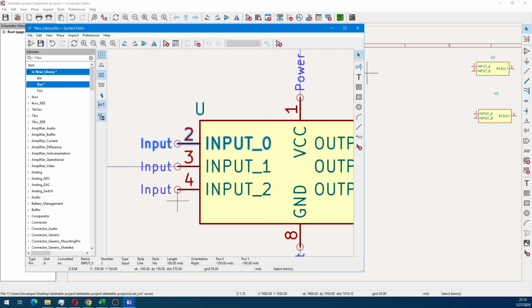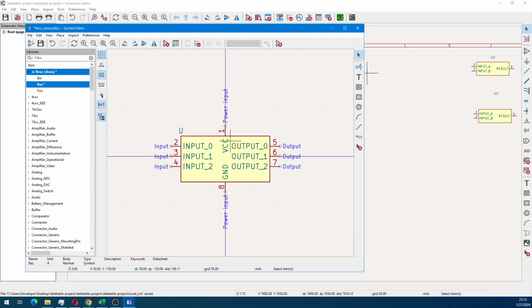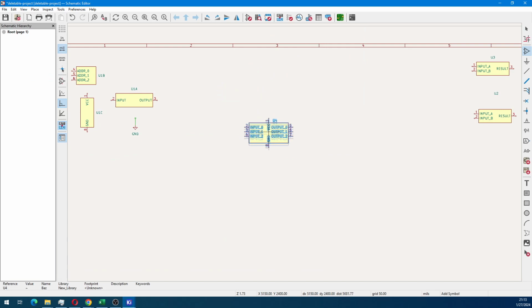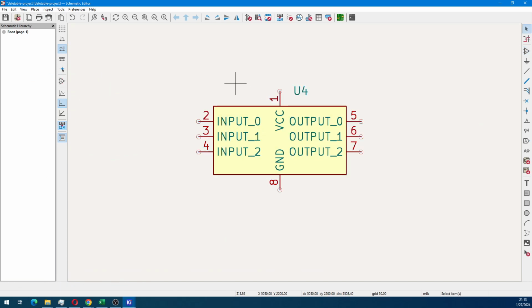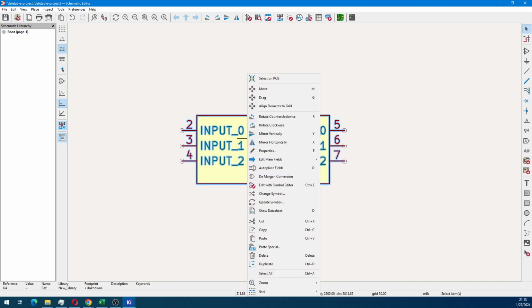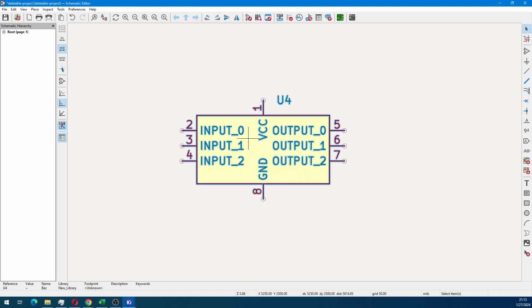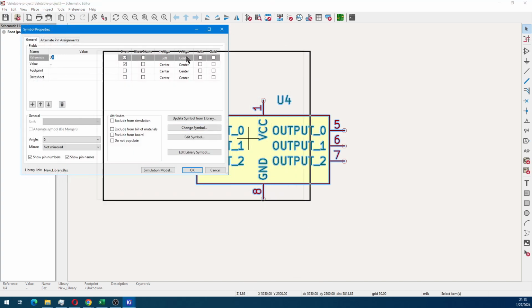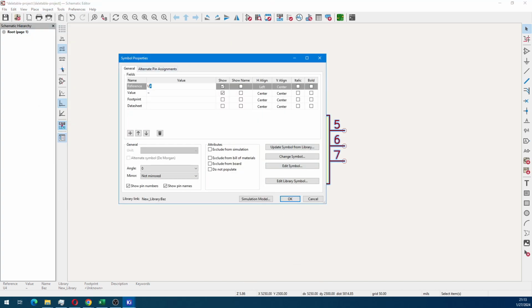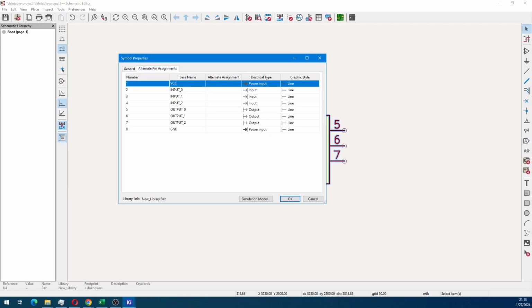So what I've done right now is I've gone back to the canvas, back to the schematic, and if I edit the part and I go to alternative pin layouts, I can go to this column and I can get a drop down that has the alternative pin names, and once I select them, it will automatically adjust the pin shape as well.